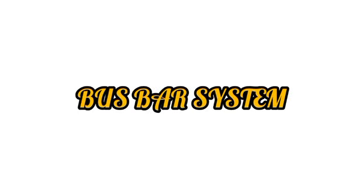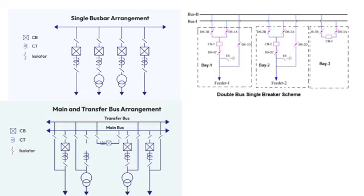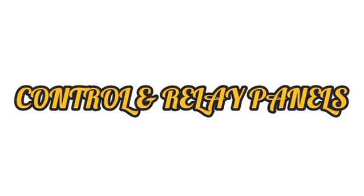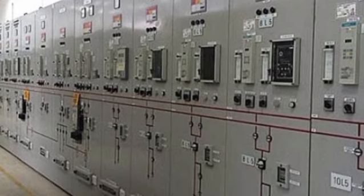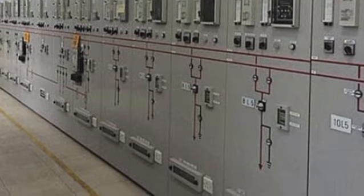Bus bar system. Types: single bus, double bus, main and transfer bus, and ring bus. Conducts power between components within the substation, material copper or aluminum, often tubular or conductor-based. Control and relay panels. House digital relays, annunciators, meters, and SCADA I/O modules, located in the substation control room or prefabricated control buildings. Earthing system.